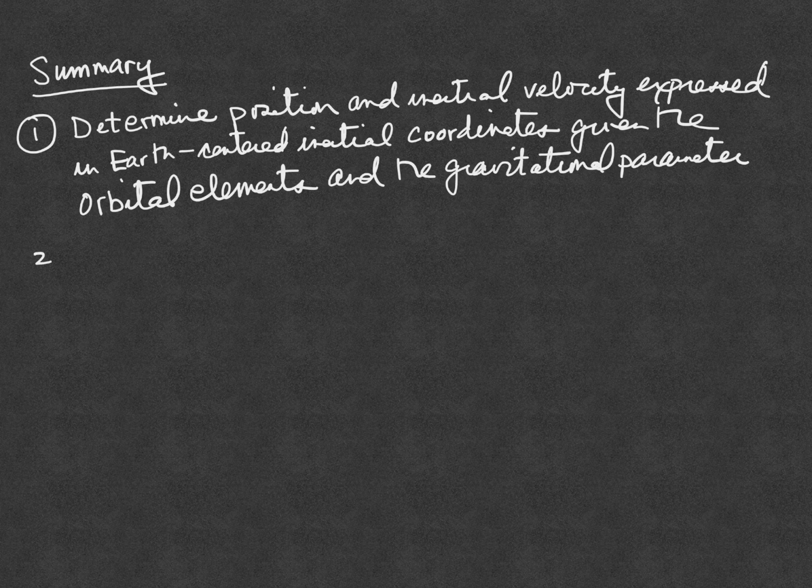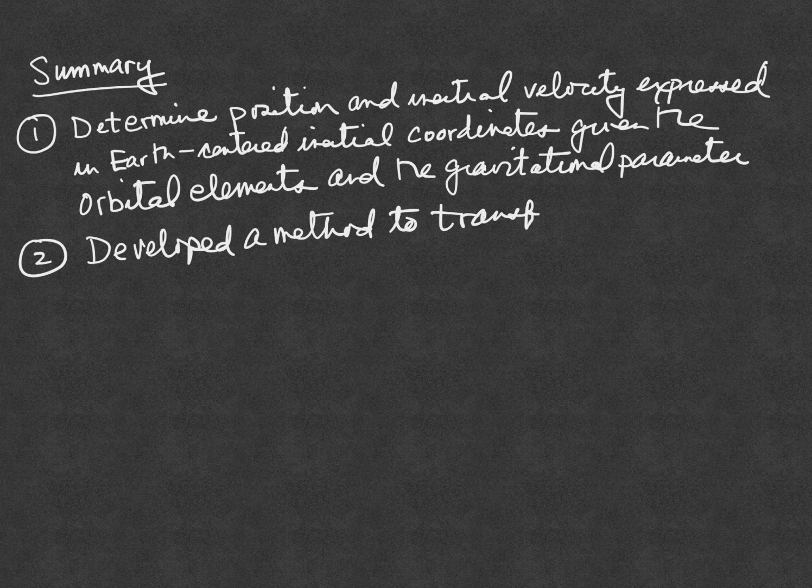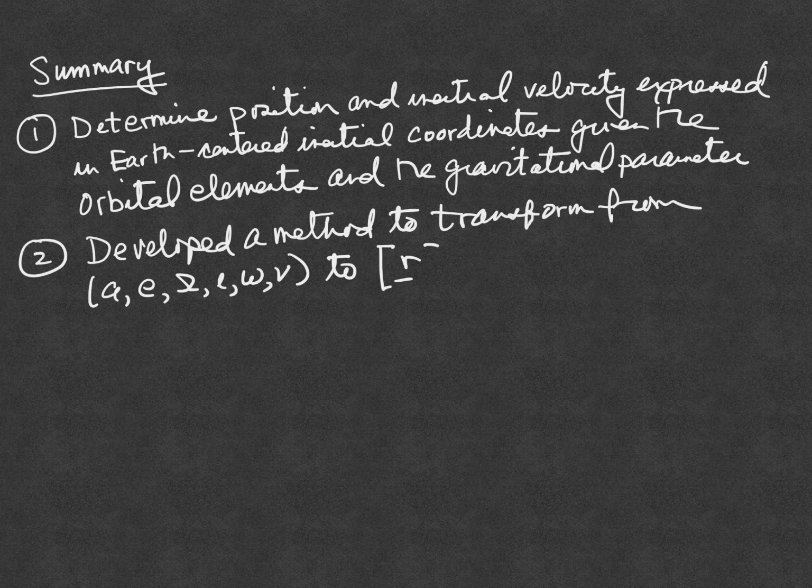In the process of doing that, we developed a method to transform from a, e, omega, i, little omega, and nu to the position expressed in the Earth-centered inertial coordinates and the inertial velocity also expressed in the Earth-centered inertial coordinates.